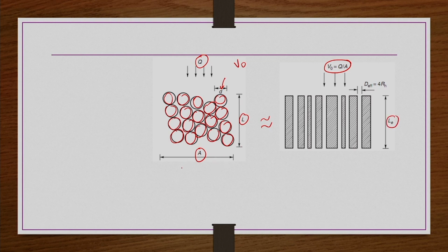Fluid particle may be travelling more than the L value, as I mentioned, because of the tortuosity. So, that is the reason we have LE here, and then whatever the void space because of these non-circular conduits that we are having, you take a D effective.